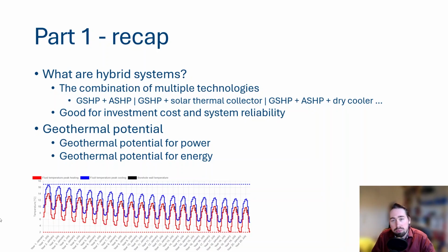So imagine if we would install some extra power onto this borefield. We could extract more heat in the first years or provide more cooling in the last years of operation, so we can exchange more energy with the ground. But looking at it from a power perspective, we cannot have more peak power since we're already limited by the temperature limits there. So that's why we say this borefield has no potential for power, but there is still potential to exchange energy with the ground.